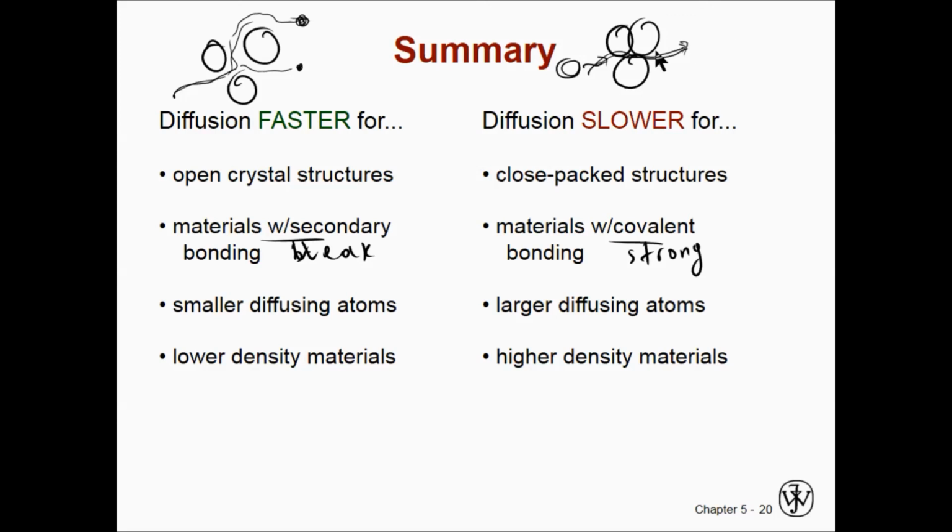So we have these atoms, elements. I have some vacancies. As this vibrates, at a certain time a vacancy will move to this one over here. It will be a vacant position, and this atom will be able to go there using vacancies, and vacancies are limited, so a smaller diffusion rate.